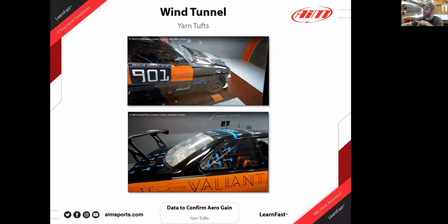The Audi video is the first one we went on, and we ended up, believe it or not, there was a difference between taping up the side vertical or just a piece of tape across the bottom. Again, I guess it depends. If you have a splitter, I generally tape up the bottom because it builds up a little more high pressure on top of the splitter. Where if you tape up the sides coming in, the center going in might still not have quite a higher pressure. Yeah, the difference between taping up the sides of the grill versus the bottom is minute, so I wouldn't really worry too much about that one. But taping up a certain percentage of your grill is always a good move if you can get away with it. There you go.